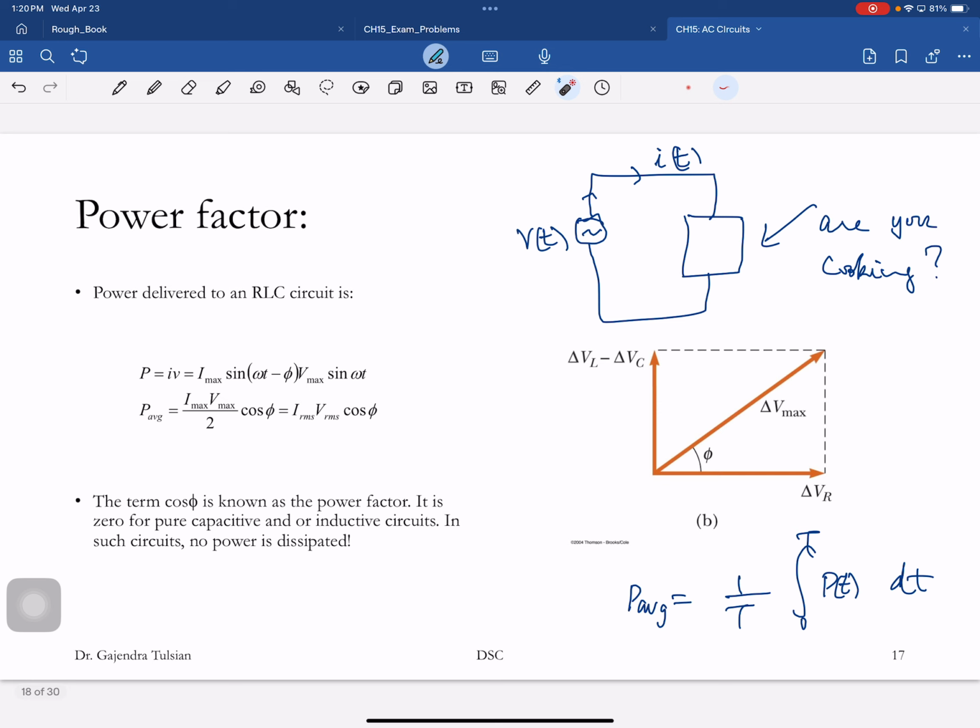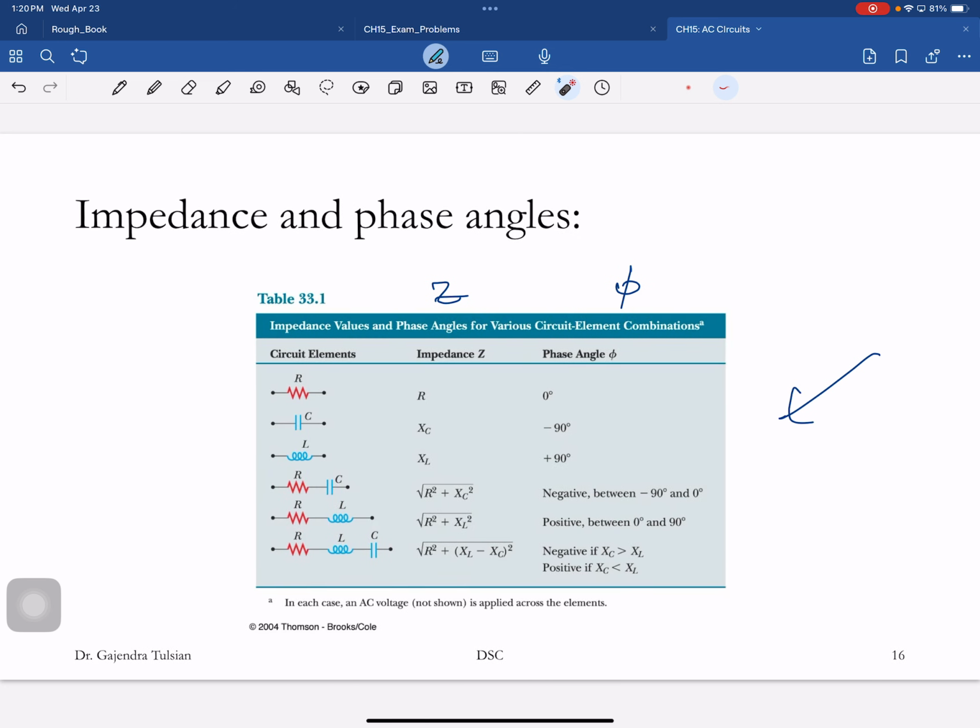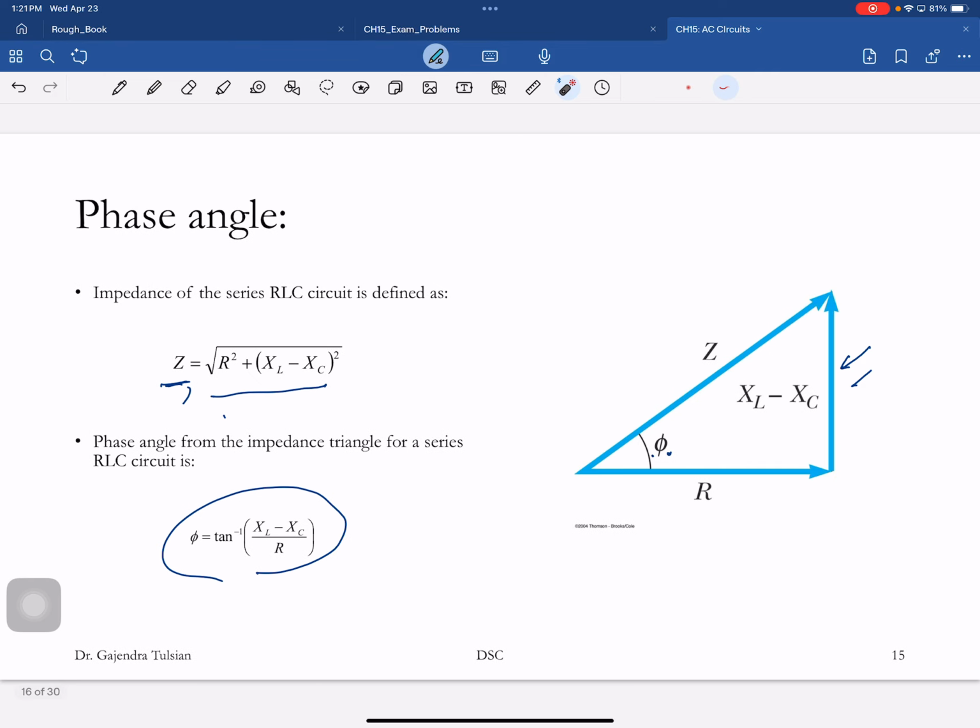Okay. So they have an inductance associated with them. So phi is between 0 and 90 degrees. Let's say it's 45 degrees. You're not delivering power most efficiently. So what do you have to do? What you do is you add capacitors such that this becomes 0 and phi becomes 0. So you add banks of capacitances in front of the city, so this becomes 0, so phi is 0.